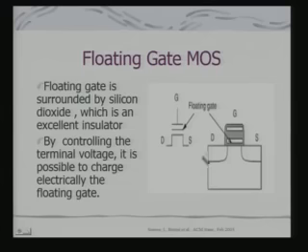So, what is the basic technology that goes into them? The concept is that of what we call floating gate MOS, and it is effectively a single transistor. Just like in DRAM we use a capacitance to store charge as indicative of the data, the same thing is true here as well. All these modern EEPROM and flash memories are built around this technology.